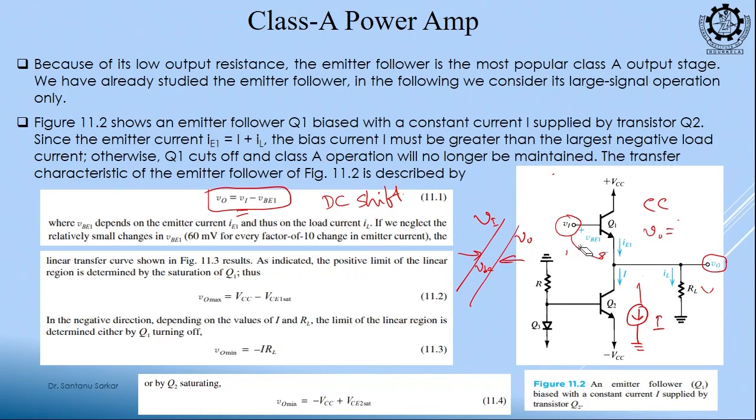Next is, if we want to say what is the maximum value of V0. So, this Vi can go to maximum of, this is one KVL loop, another KVL loop is this. From the input side I can do one KVL, from the source also I can do one KVL. So, what is V0? VCC minus, what is this drop? VCE. So, another V0 is VCC minus VCE.